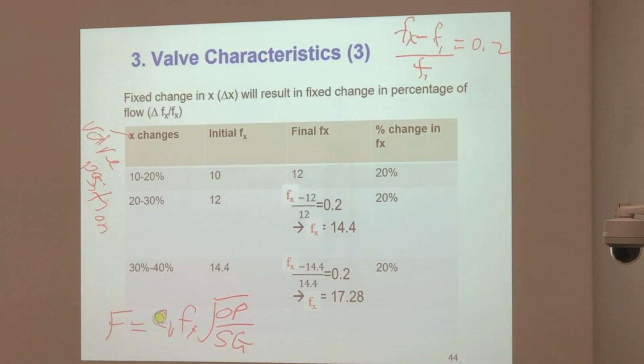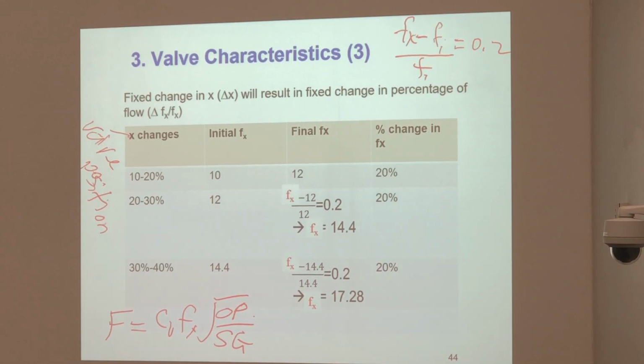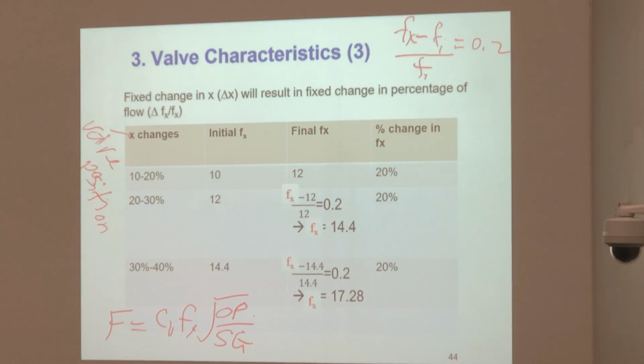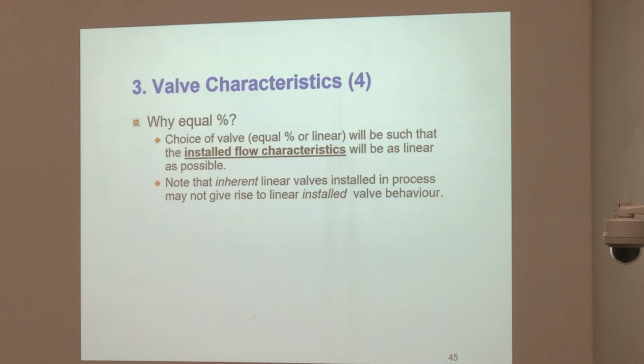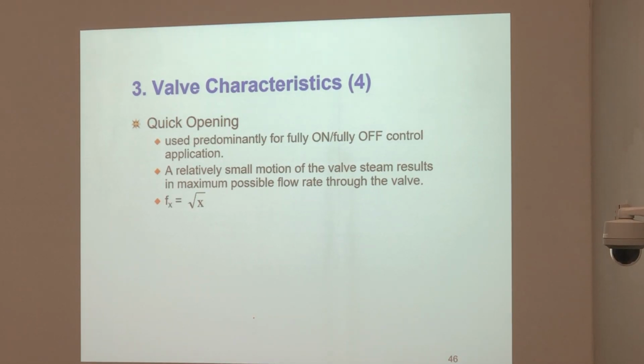This one will not change. This one depends on the valve position. This one we can calculate from the formula. Alright? Okay? So it's not always straightforward to give you fx equal to x. It depends on the valve characteristic. Okay? This one is not important. Quick open, yes.